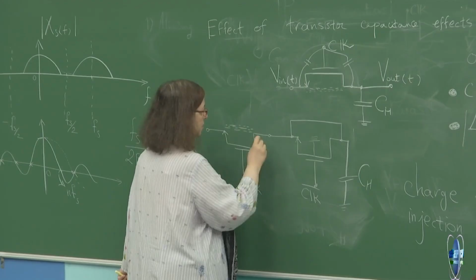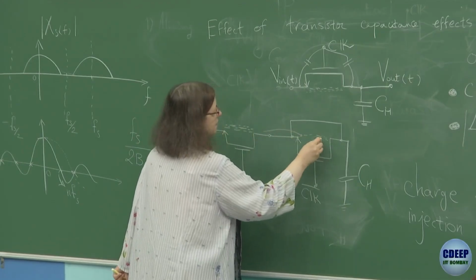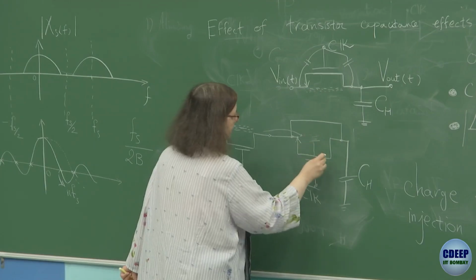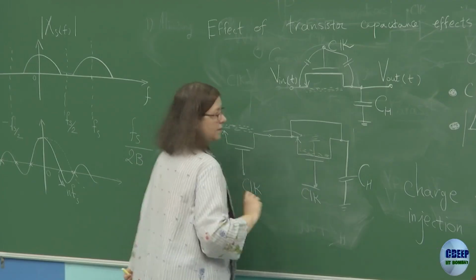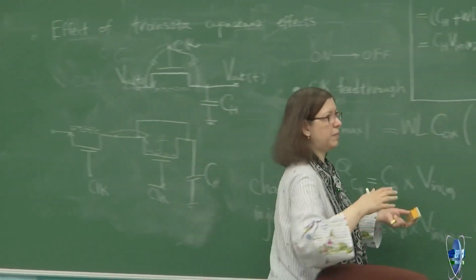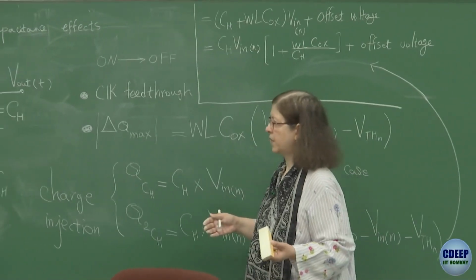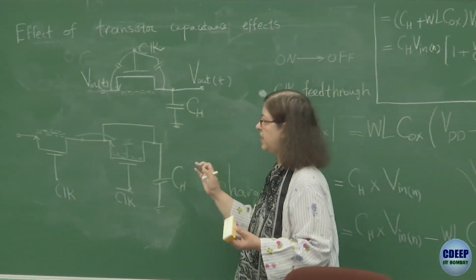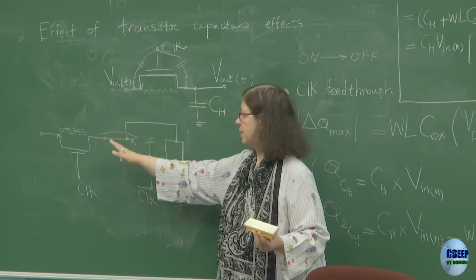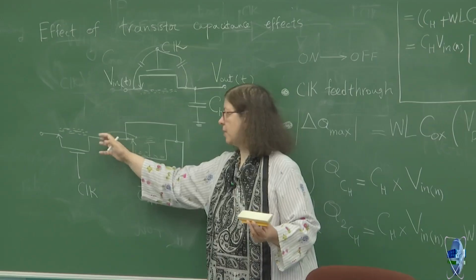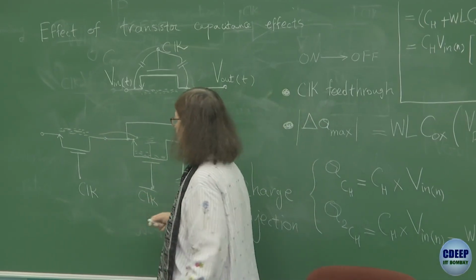This needs charge. So charge actually will go to the channel of this transistor. Oh, no, I should not show it there. Here. Right? So it's like from one bucket, it goes to another bucket. These two transistors have to be exactly the same, so that the same amount of charge which comes out here can go here, because they are experiencing exactly similar conditions.